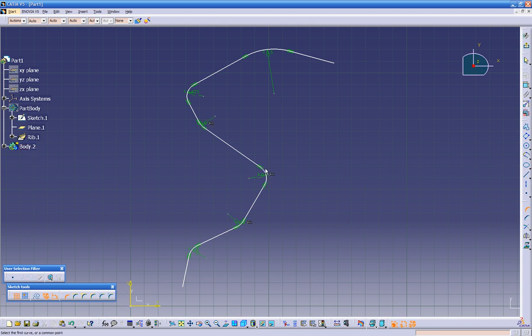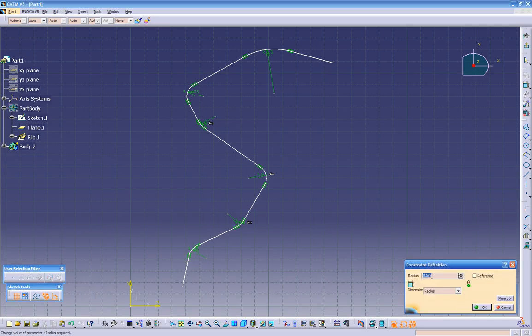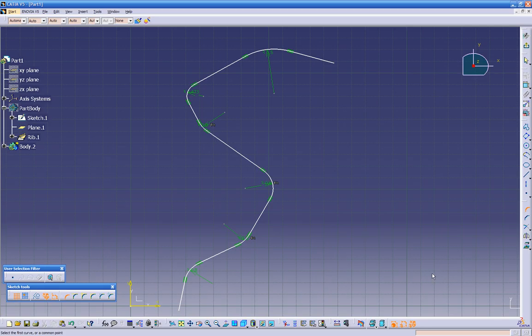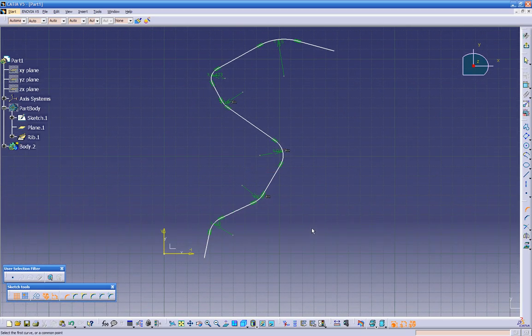But you see it's carrying the formula with the radius, because the moment I change this right here, automatically it's gonna update it because they're all linked together. So watch what happens if I double click here, I change it to 800, automatically update all the other ones. So that's pretty cool right there. Let's get out of the sketch now.